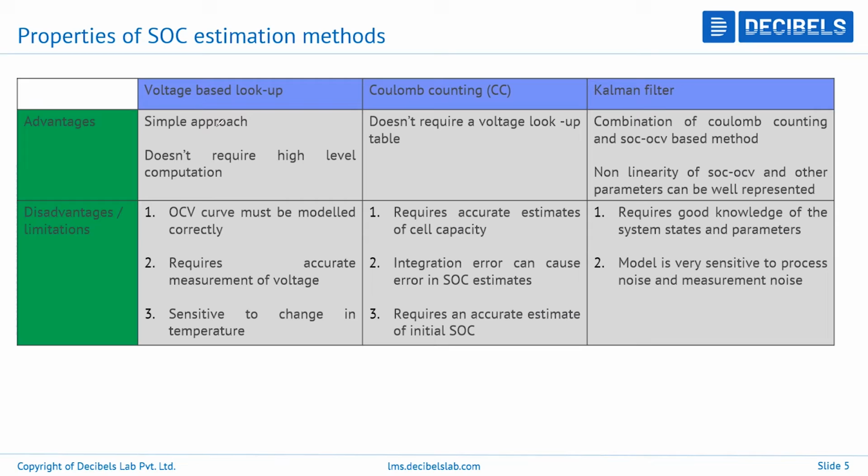First and foremost, the voltage based method, we have seen it is very simple. It does not require any high level computation. It just is a simple one-dimensional map that compares the recorded, or measured, voltage value to the pre-established values of state of charge, right?